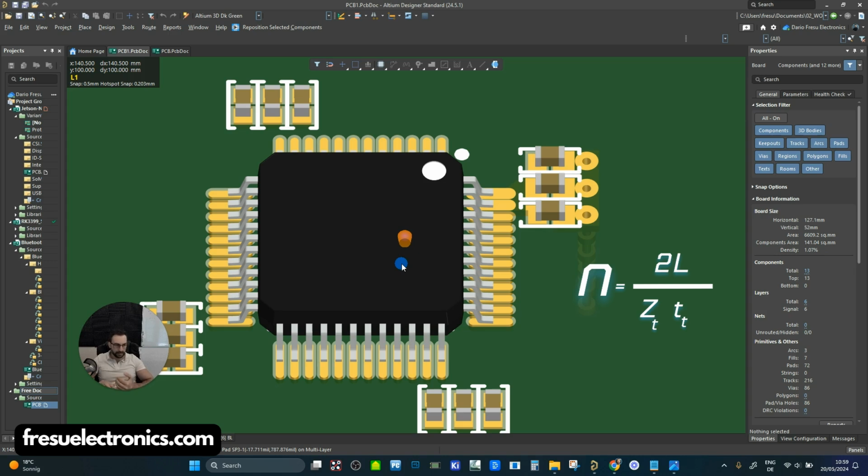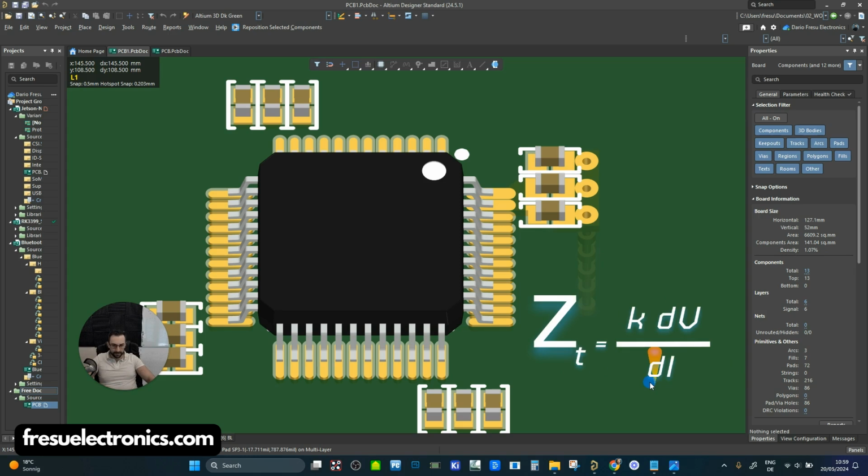And by that, we're going to find the number of capacitors that we need in order to achieve this target impedance. So when we're calculating the target impedance, we have these adjusting factors that take into account noise, temperature changes, parasitic elements, and manufacturing tolerances, so that when you're doing the calculation, you can easily adjust the target impedance requirements that you have.